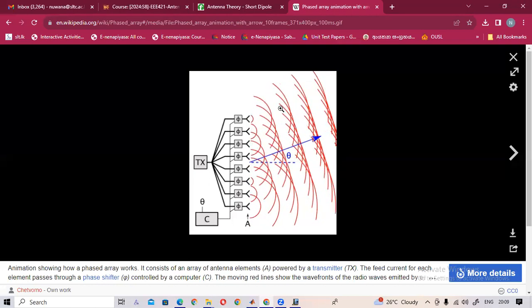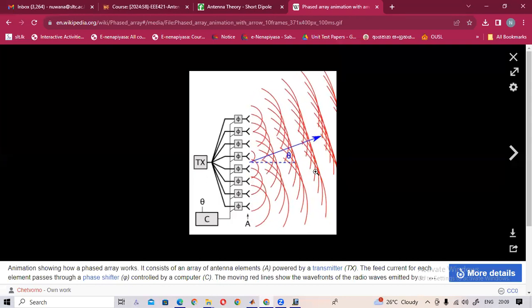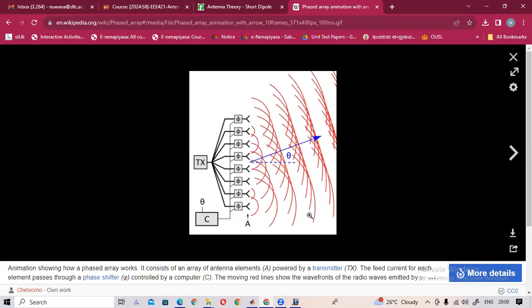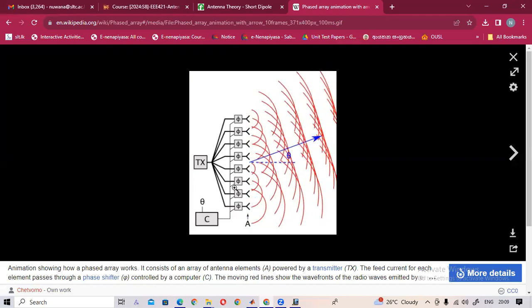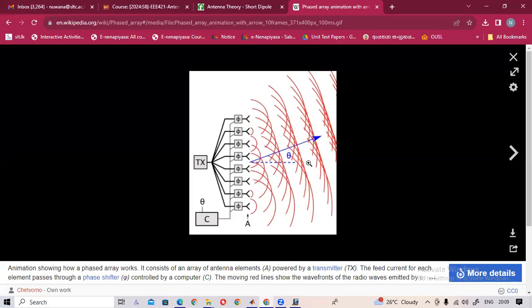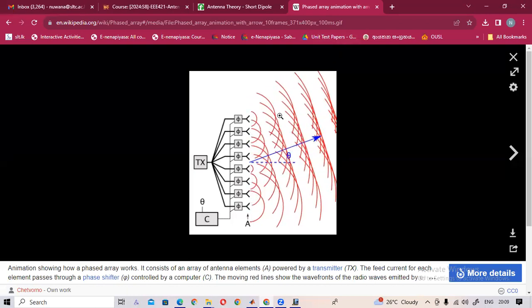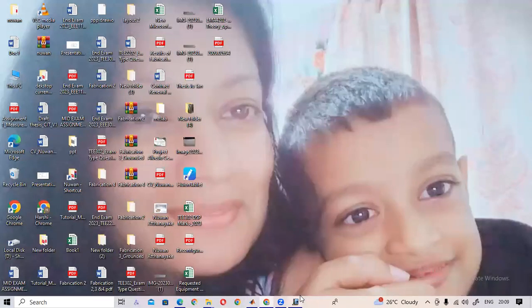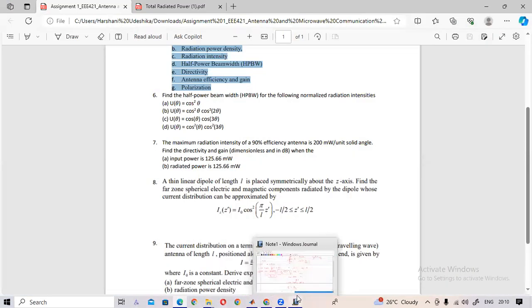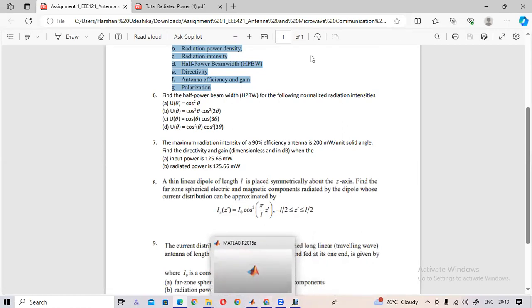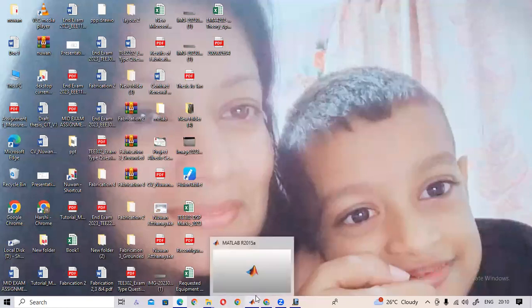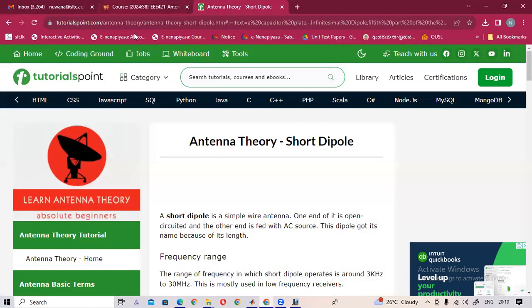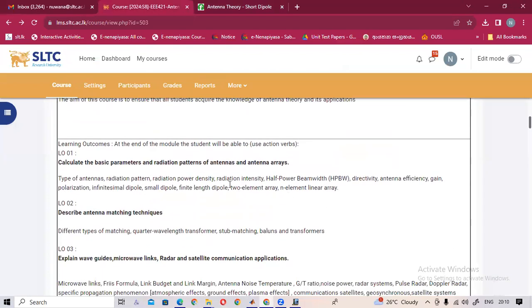Electronically scanned array, because it can scan. It can send the signal to any direction. The direction can be changed using the delays. So this is one advantage of a phased array antenna. Here they are expecting only the idea, but if we have time, we will see how we can beamform using the array antenna.